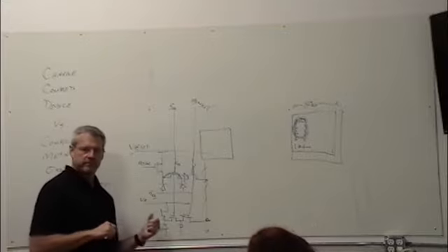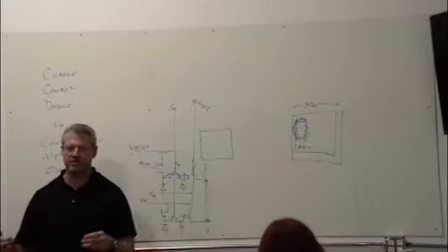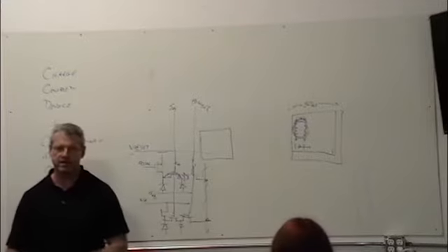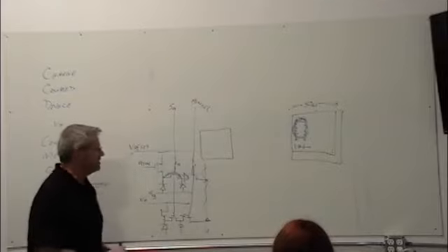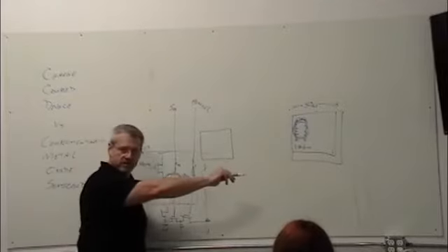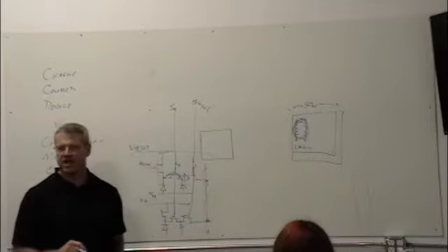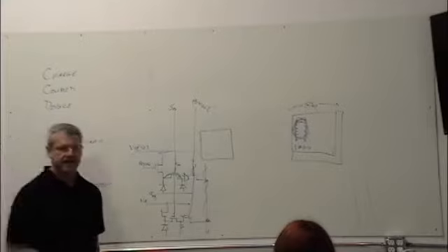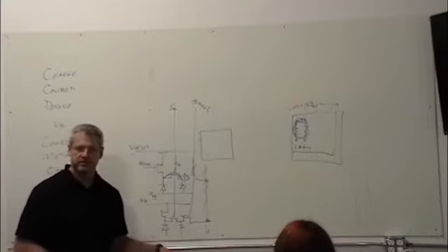So the intrinsic noise and hole traps and things like that that cause weird effects are going away. Because I shift this straight out, I don't have the CTE problem going across the top. I don't need to worry about a process that's so clean that I'm going to get 5 nines of efficiency out of it. I can have 99% efficiency out of it, and it's good enough.